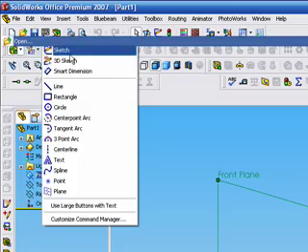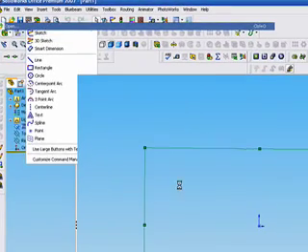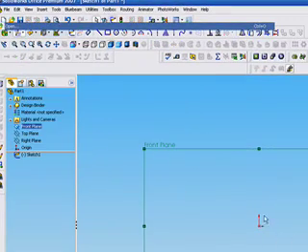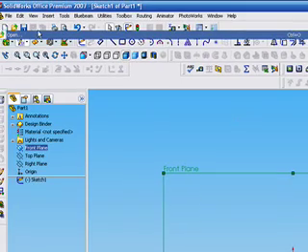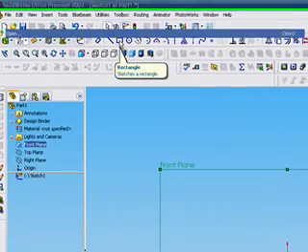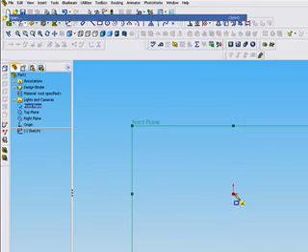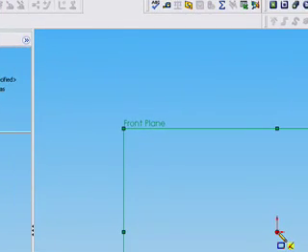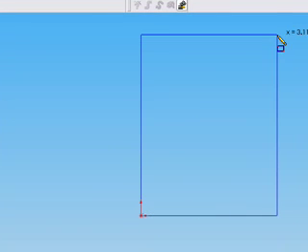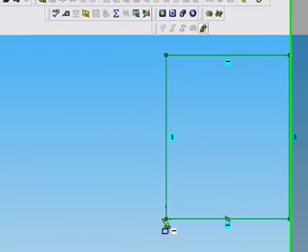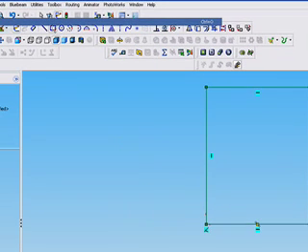In here we're going to select our sketch, and that turns our plane normal to us, which basically means it's parallel to our face, or you're essentially looking at a chalkboard on a wall. It's whatever you want to think about it. Now we're going to select the rectangle, and this here is the origin, and it just helps lock things down. You don't necessarily have to use it, but it becomes good practice.